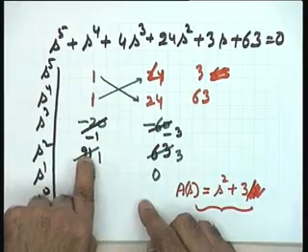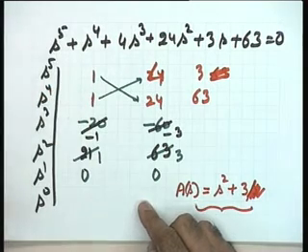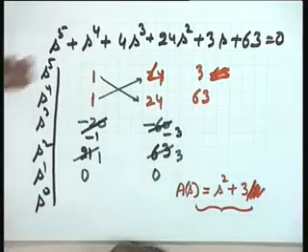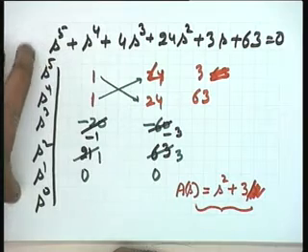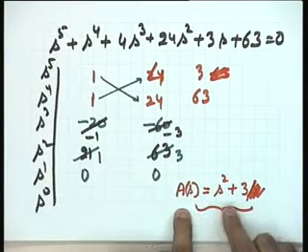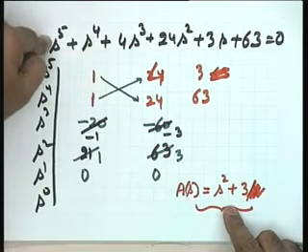If you come across an all 0 row, the conclusion is this: the auxiliary equation which you form from the row one row above is a factor of the original characteristic polynomial. This result does not force you to conclude that the system is marginally stable. Can we say that? This particular pair of roots on the imaginary axis is definitely a factor of this characteristic polynomial.